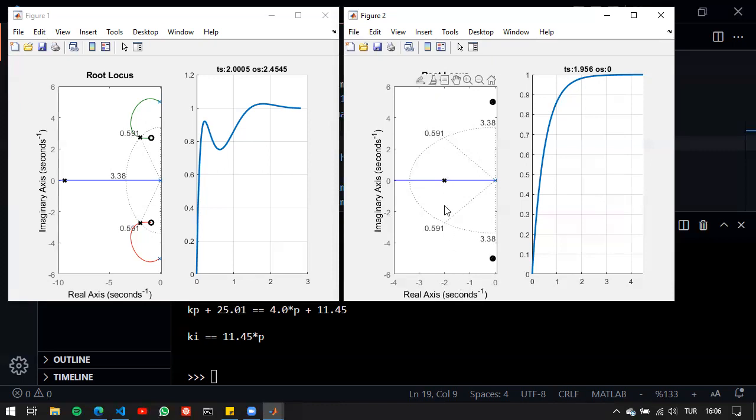And we also know, by the way, where the intersection should be, because we want to be on the settling time line here. And it's equal to 2 here. The pole here is 2. So they should coincide at 2, and one should go up and one should go down. In that case, and I'm going to show that case in a moment, I will just look for a gain that assigns the poles to exactly this point and this point here.